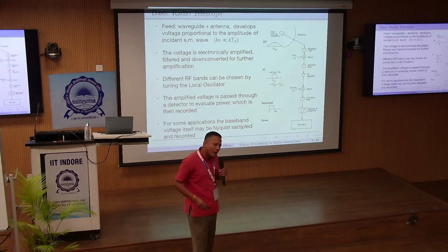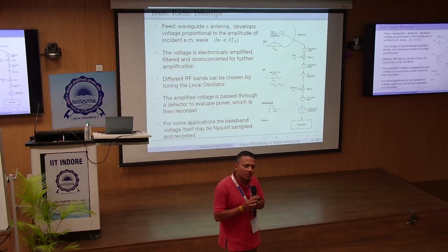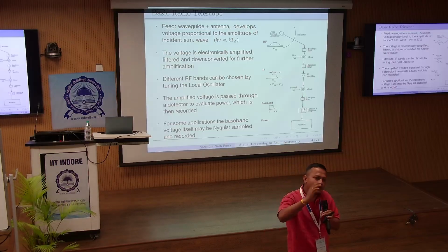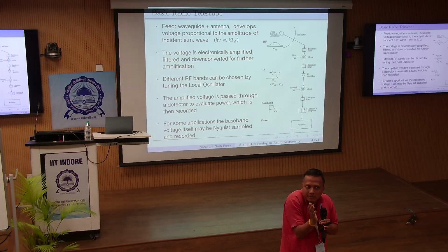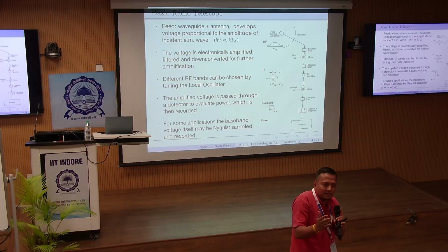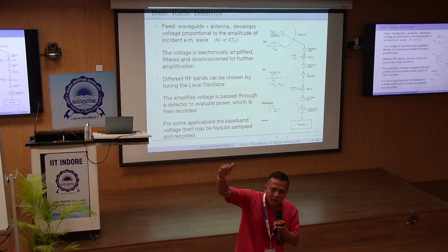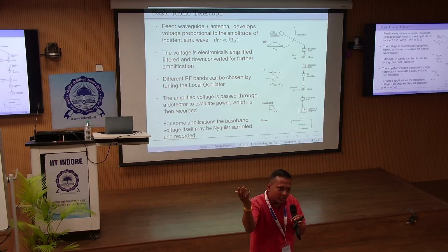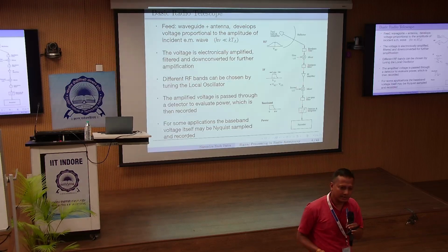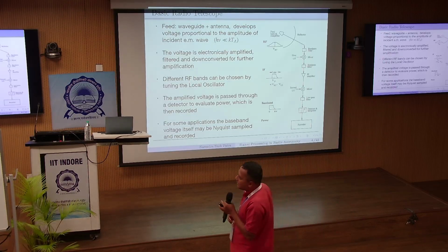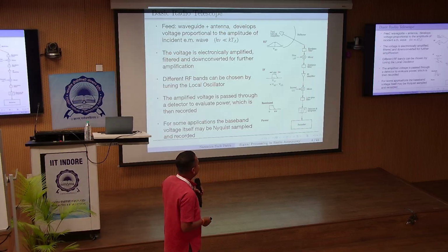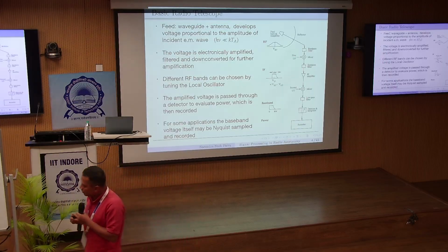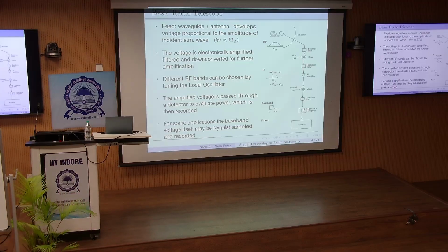So what are we interested in? Let's say I have a sine wave at 1.4 gigahertz sitting. I am interested in the nature of its ups and downs, right? I don't care at what frequency it is sitting, right? So what I can do is mix that signal with a locally created signal. So let's say I have a signal.